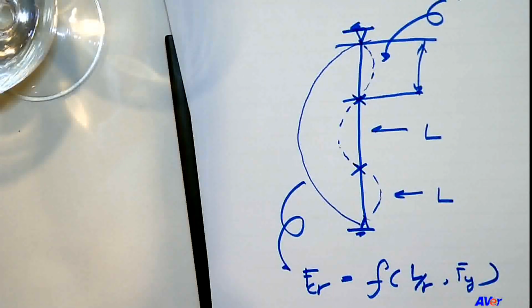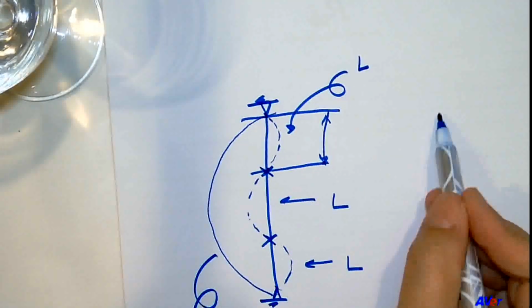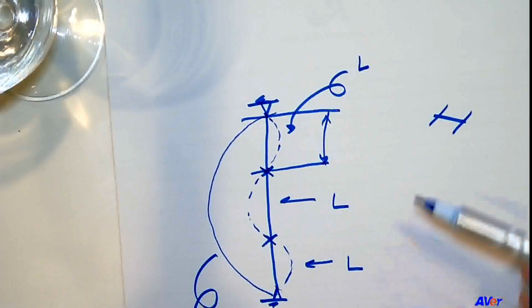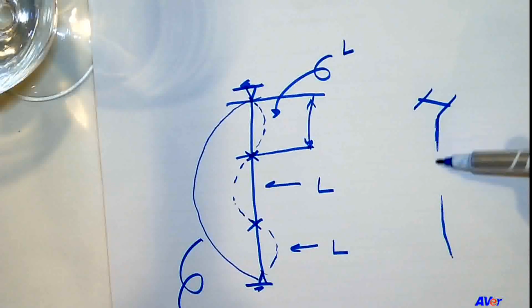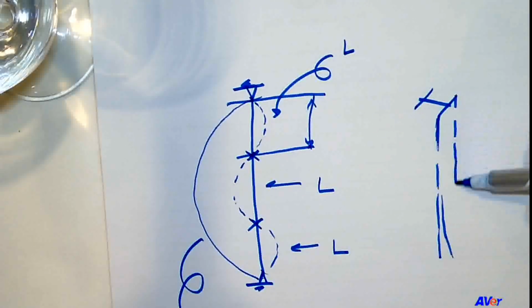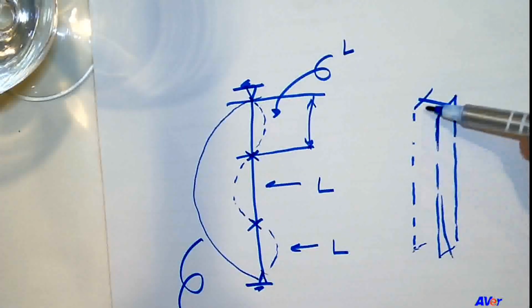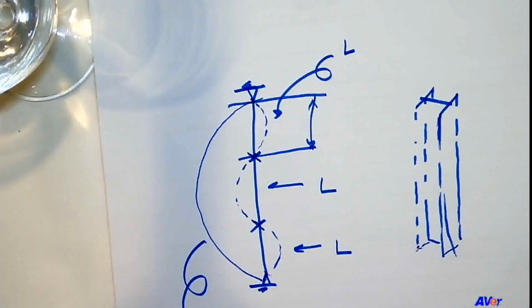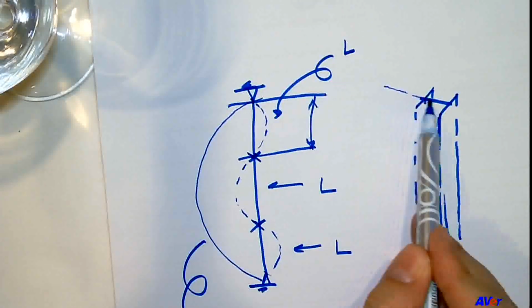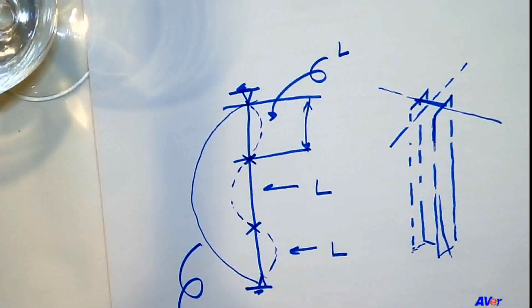And of course, now we don't have the column as a line like this. And you should know that when we have a column that is a shape of an H like that, now we have, let's say, the radius of gyration and moment of inertia different for two axes. So when you have a case like this, you are going to need to check the slenderness ratio of both axes, right?